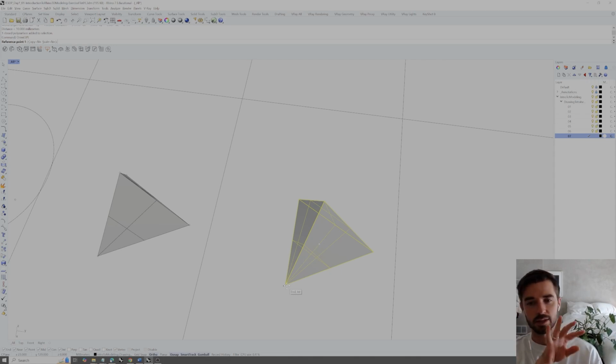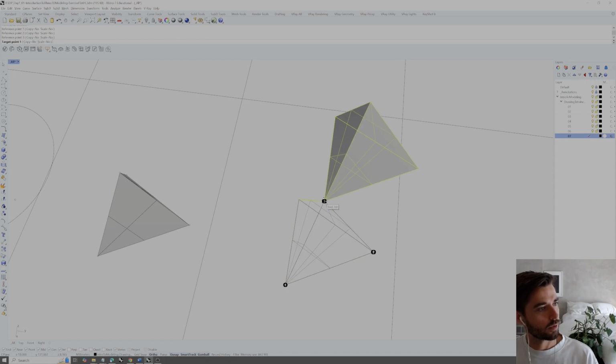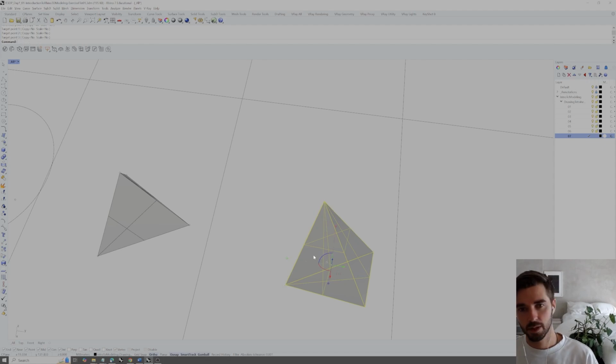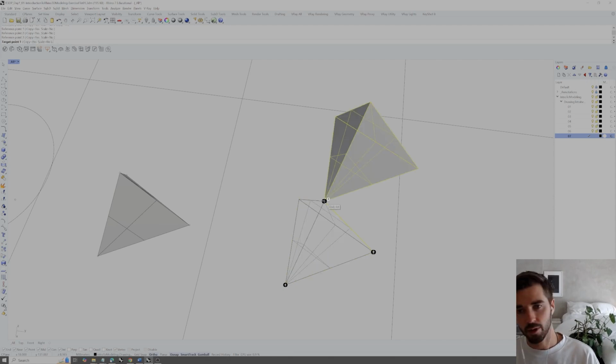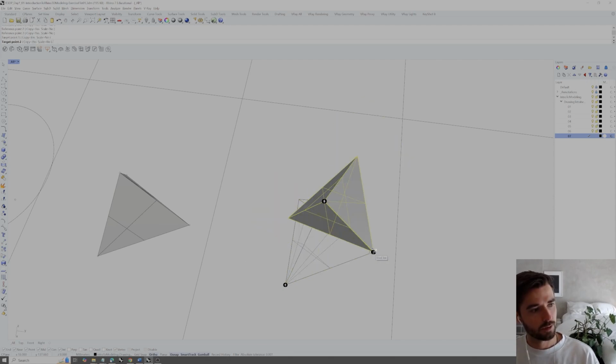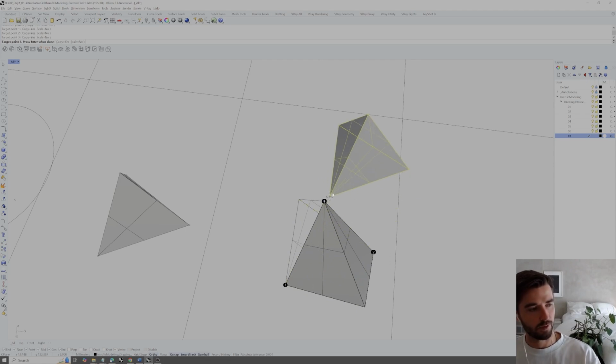What this does is it basically copies the thing onto itself, but by kind of translating it and flipping it. So reference point 1 is point 1, 2, 3, and then we're going to go just in the reverse order, 3, 2, 1. So we flipped it. Now if we have copy on when we're doing that, which is one of these sub options, so copy, yes, we can do that same thing clockwise, 1, 2, 3, all on the same face, and then 3, 2, 1 on that same face.